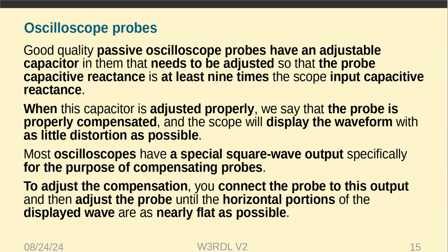Most of them have a little adjustable capacitor, usually in the base of the probe or somewhere on it, that you can adjust to adjust out stray capacitance.